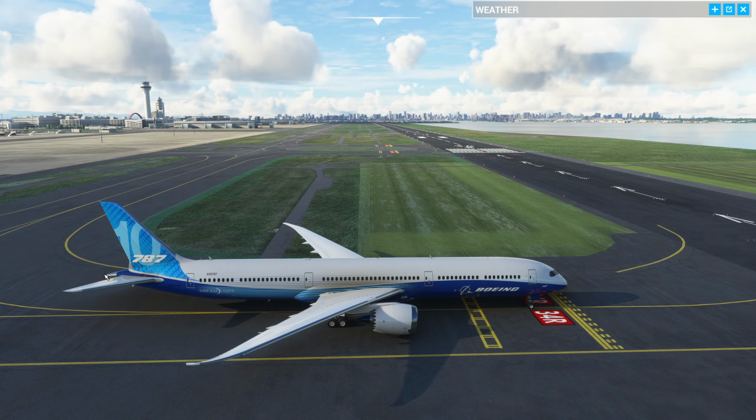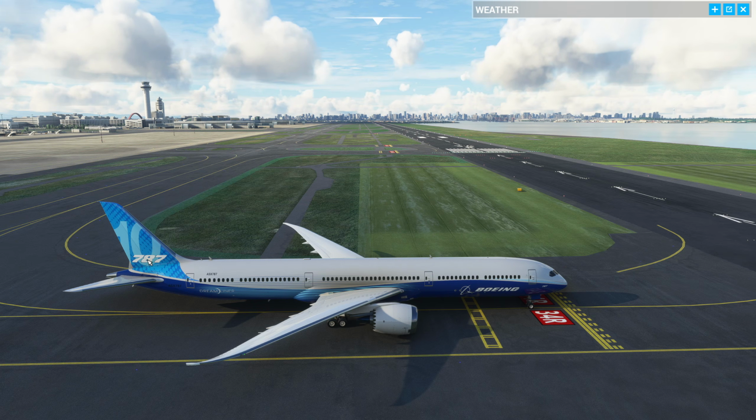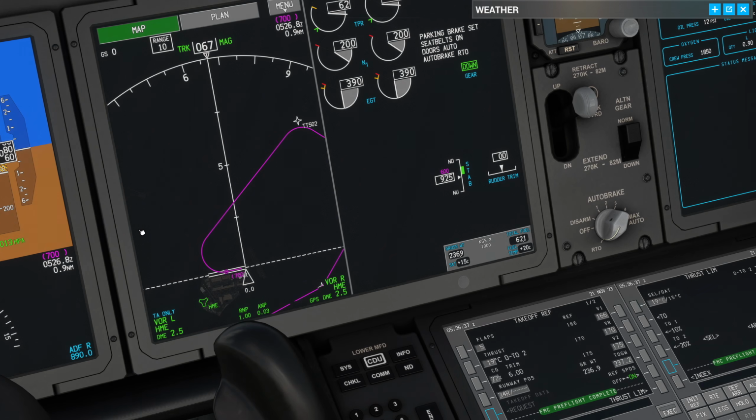So this stabilizer here, on the Boeings, after you land, it just leaves it at whatever position it was at. So it's always in the wrong position. The Airbus is quite clever. After landing, it sets it back to neutral during the rollout, and that way it's in a pretty reasonable position for the next flight and only has a little bit of movement needed usually. However, on the 787, it could be way out because of whatever it was used on for the last landing, depending on their CG and speeds and all that. So we need to set it to 6.